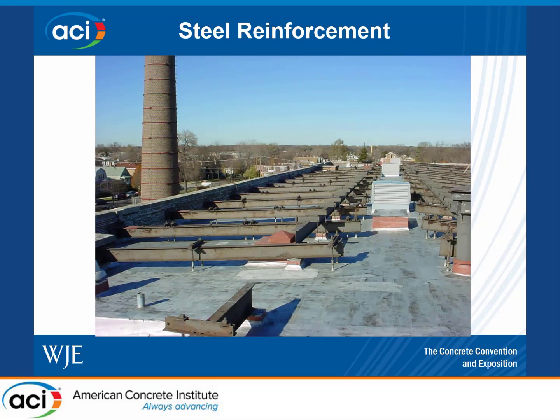To give you an idea of how much steel was installed, this is the roof level of the building, and you could see steel beams installed in almost every bay. The tie rods extend down through the roof structure to connect to a second grillage of steel in the attic space to shore up the entire reinforced concrete roof structure at the vast majority of this roof. The secondary grid of steel installed below the roof structure was hanging from those hanger rods.